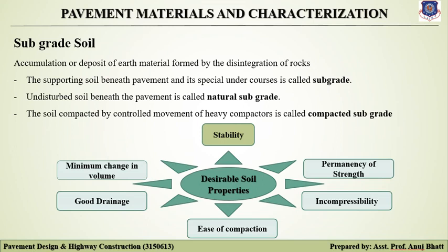We can say the stability of subgrade can be improved by soil stabilization. Sometimes the thickness of various layers is increased to improve the stability of the pavement. When a road is constructed in embankment, the factor of safety for slope stability should be 1.5.